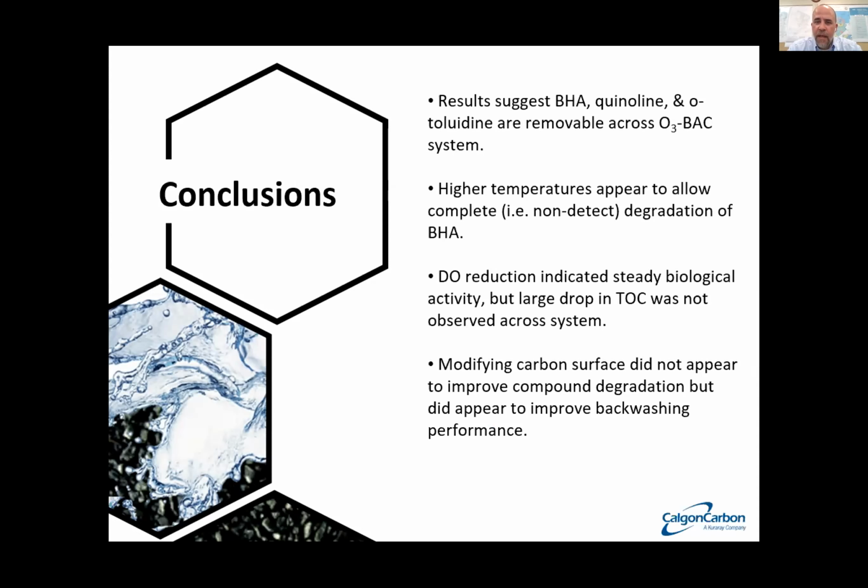DO reduction was steady, but there was not a large drop in TOC. One thing we can examine in the second part of the study is if a higher ozone dose will hit more of that, but it did not appear that those responded very largely to the ozone. Another benefit in an ozone BAC system is that the ozone oxidizes the TOC molecules, or the molecules that comprise the TOC, so that they are more amenable to biological degradation. We did not in this case see that, but again, it did not impact the removal of the target contaminants.